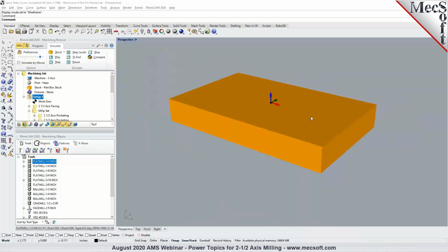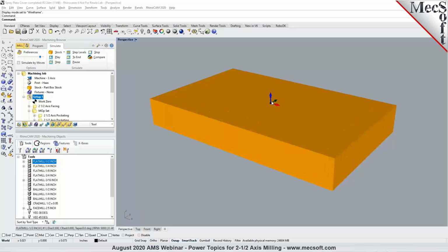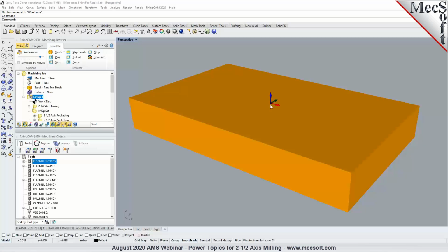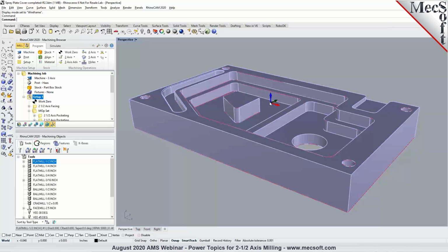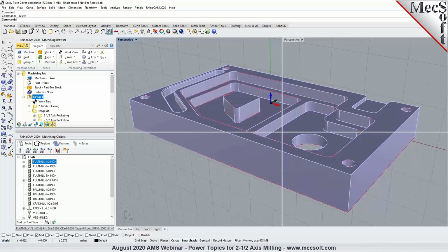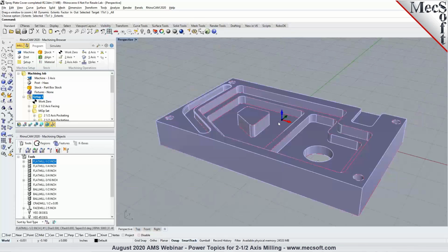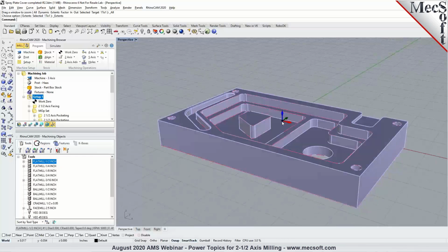So in this particular example, you will notice that the world coordinate system origin, also known as the WCS, and the machining coordinate origin are currently coincident. Which means when you first import your part or create your geometry in the CAD system, the CAD system origin is also by default the location of your XYZ 0. In this model, this is where we have your XYZ origin.